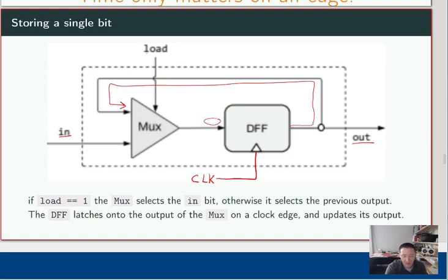So then what that means is that with this load bit, if we set load to be 0, we're going to just simply take in the current value that we have and not load anything new. A clock edge happens, and we just keep restoring the same thing over and over again. But if load changes to 1, what that's going to do is take whatever is on the input to this bit chip, pass that through the mux and store that. So therefore, it's a self-supporting feedback loop.